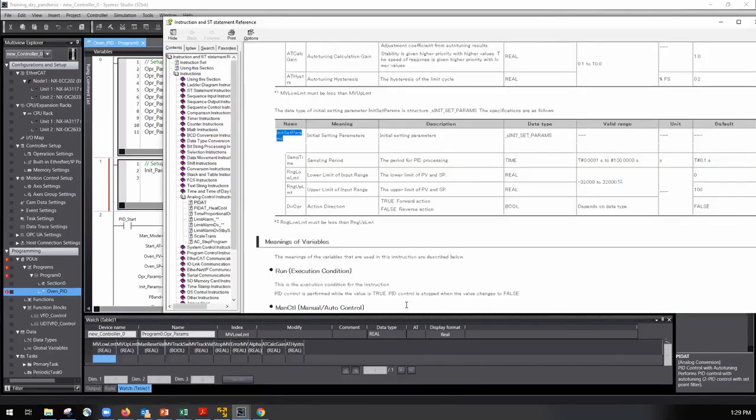And what the sample time specifies is how frequently we execute this block. So their recommendation is 100 milliseconds, but we could do this every 100 seconds if we wanted to, if this was really not an important calculation or not a very responsive process.